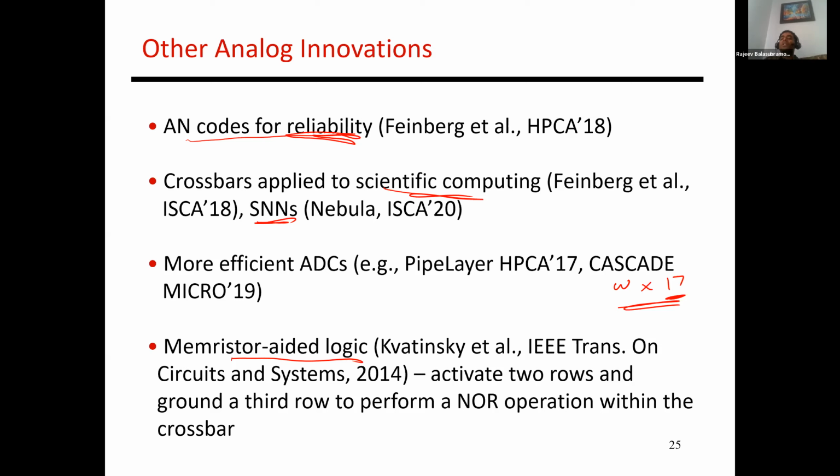And so in-memory computing is basically saying that this main overhead can be overcome by placing all of those models into these many crossbars. And then I don't have to move those weights anywhere else, right? The inputs basically show up over there. The computation happens inside the array. And those results basically propagate from one crossbar to the next, right?